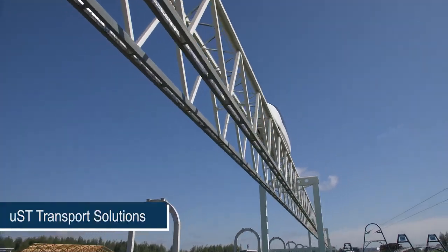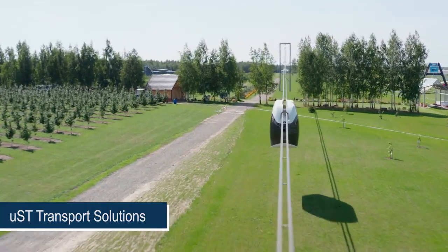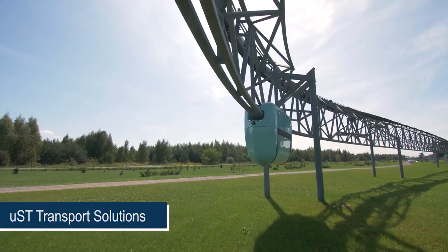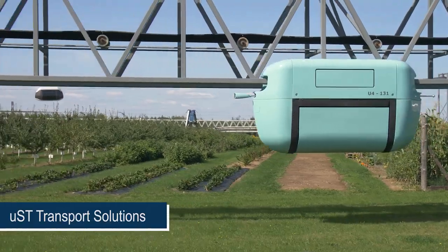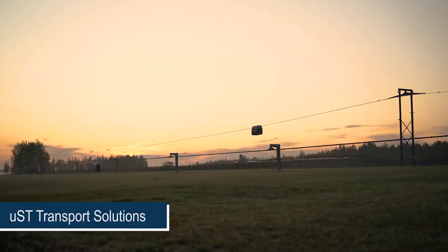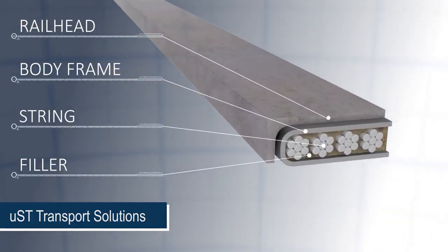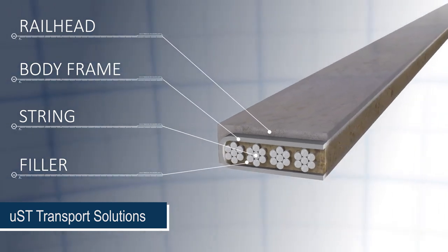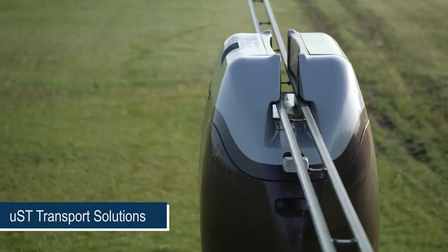The transport and infrastructure solutions of Unitsky string technologies are highly efficient complexes in an overpass design. They surpass all alternatives available in the modern market and provide new standards of mobility. A key element of the technology for creating pre-stressed transport overpasses by Unitsky string technologies is a string rail. It is a steel or composite beam containing a bundle of wires, strings, pre-stressed with stretching in its core and fitted with a rail head.